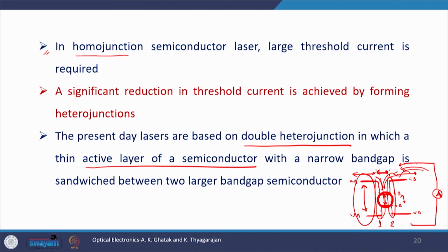The barrier levels not only confine the charge carriers, but they also play a role in guiding the light. Therefore, they make a waveguide out of the laser, and we see a very beautiful output: directional, almost monochromatic light from these double heterojunction semiconductor lasers.